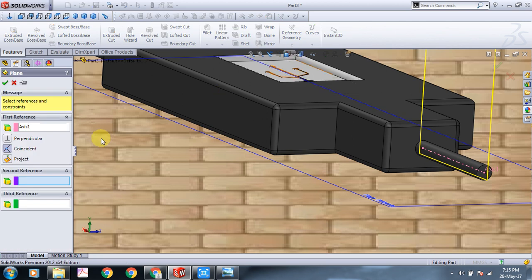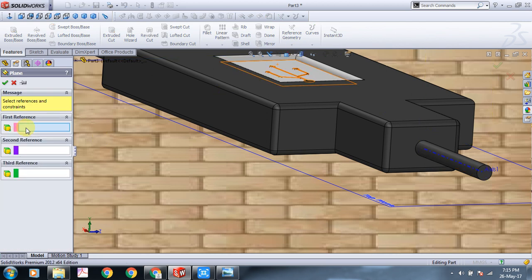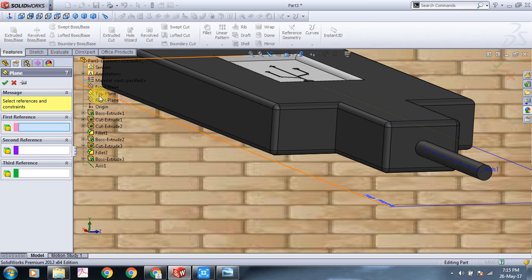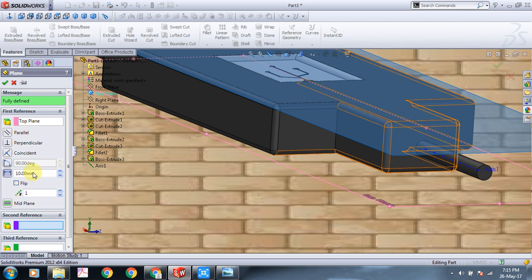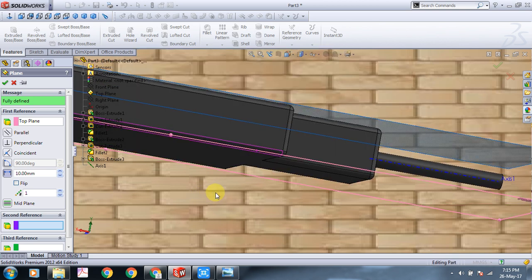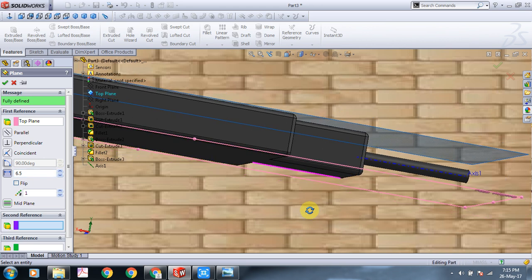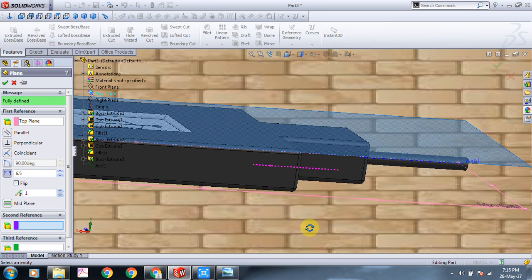When you are working with the right dimensions, you will have the plane exactly where you want to put it. So when I click OK, this plane will be shifted to the boundary of this cylinder so that I can make a feature on that cylinder. Now click on the plane, bring it to normal. You can bring it to sketch,